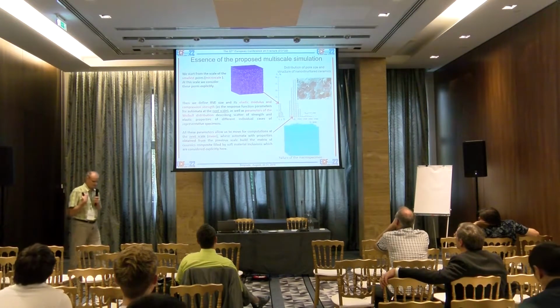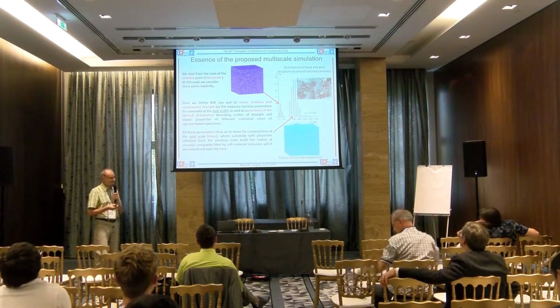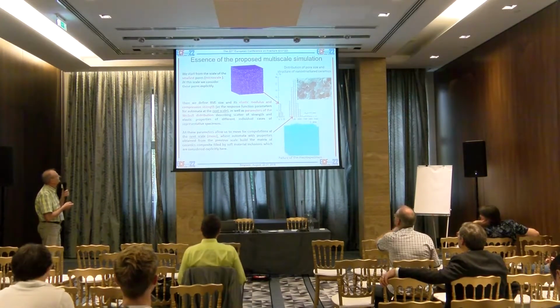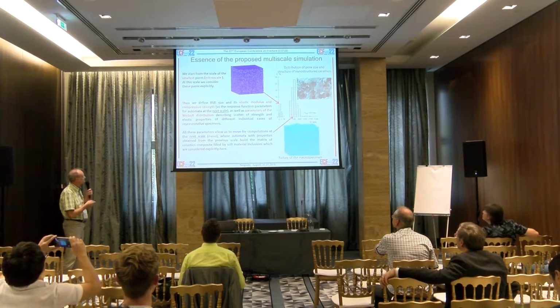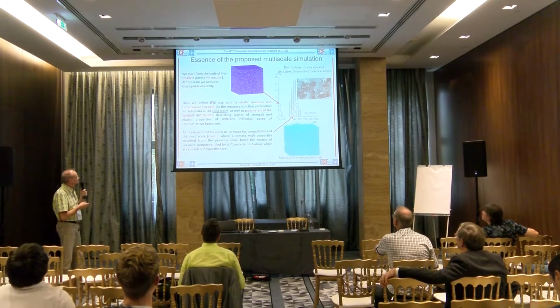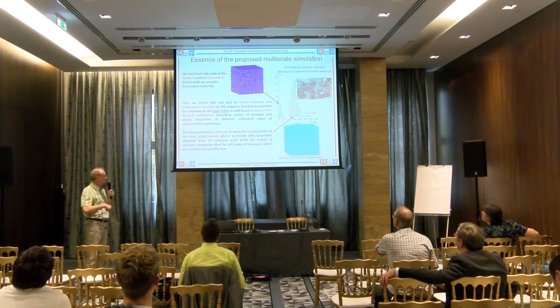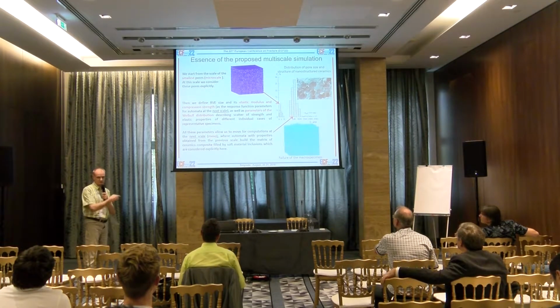And I would say that actually it may be considered not only for this particle-based method, but also for the finite element method, I think. So we start from the smallest pore size. We consider, let's say, a squared particle specimen and generate pores explicitly. And then we try to simulate uniaxial compression. We get the stress-strain curve.